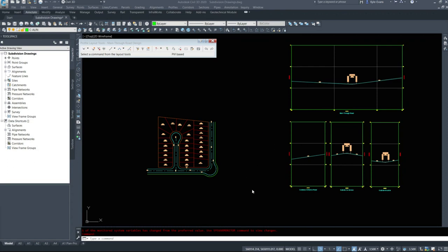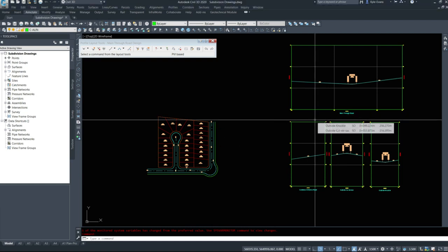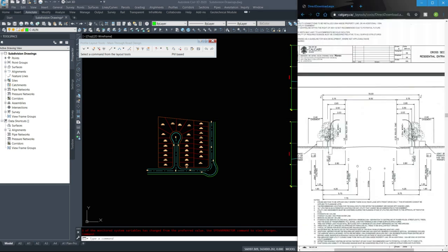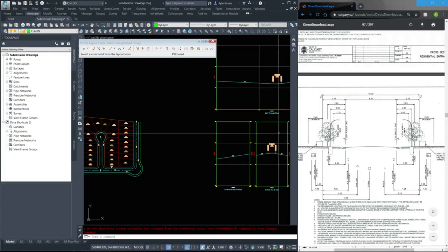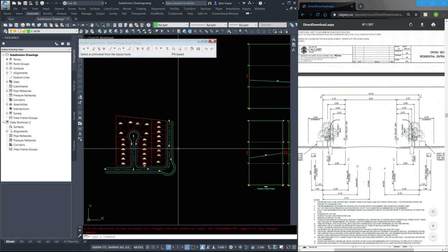In this next video, we are going to look at creating the assemblies for our corridor and our residential design. Now, we only have one residential road. It's one road type. It's in the detail that we had looked at before right here. And I just have that off to the side, so I'm going to minimize my Civil 3D just so I can see that while we're doing the work here. So just the one cross section that we'll have to build.